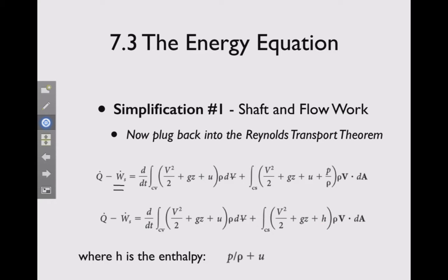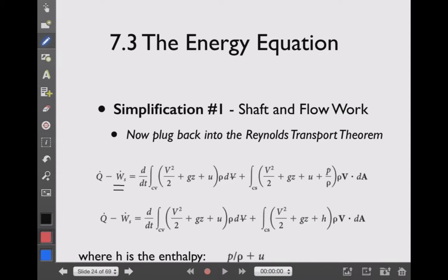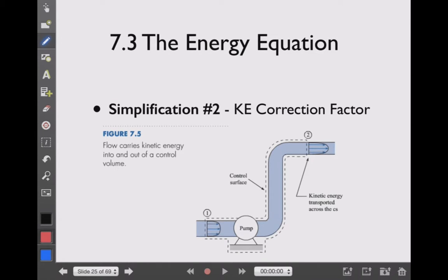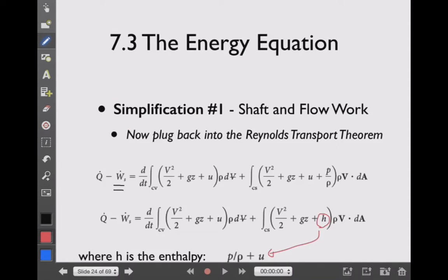So I'll just circle this in red as being something. This is enthalpy in this case, not head. It's kind of an annoying thing here. But in any case, suffice it to say, we've got this equation here. I'm going to rely on this equation going forward. And we're starting to see some things in here that make it look like Bernoulli's equation: pressure and altitude and velocity terms. We still need to deal with these U's, and we still need to deal with the shaft